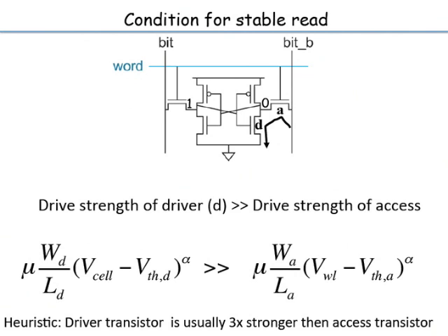You could have a full PMOS transmission gate, an NMOS PMOS pair based multiplexer, but that increases the area overhead. Remember, again, we want to keep area small. So we have done away with the PMOS for this. Will you explain the threshold? So now let's come back to this.